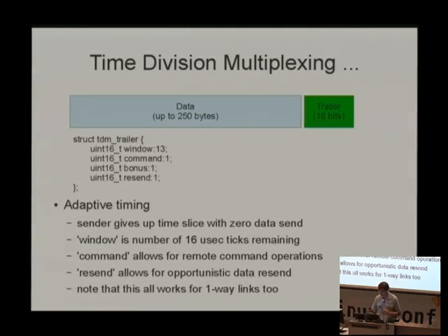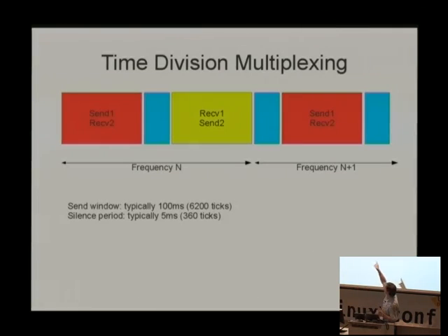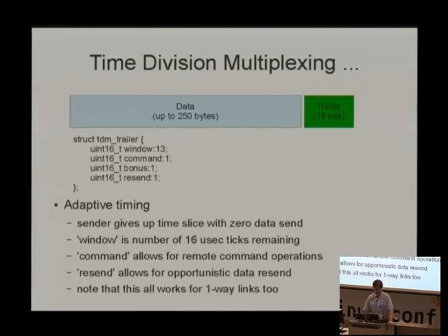Okay, so if we go back to this transmission window in the previous one, the red section, it's sending lots of packets, 6, 8, 10 packets in that red section on the left there. And each time it sends a packet, it puts this little trailer on it which says how many ticks it thinks are remaining before we're going to switch over to the next one. And those 13 bits mean that any one packet getting through is enough to synchronise the clocks between the two radios.